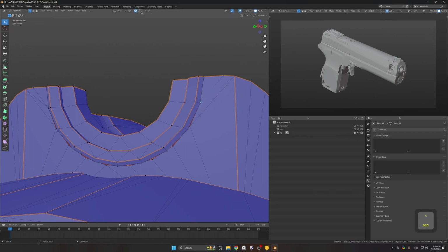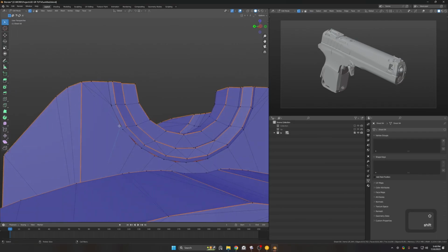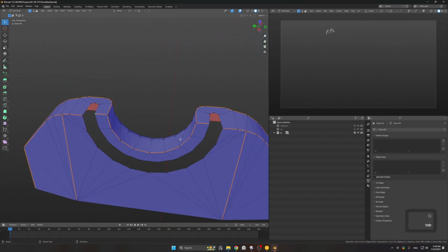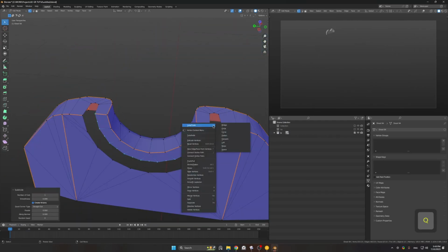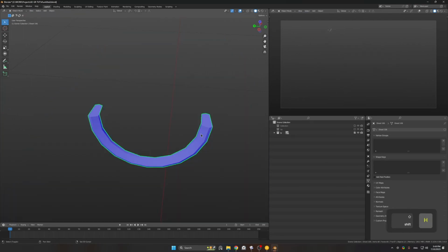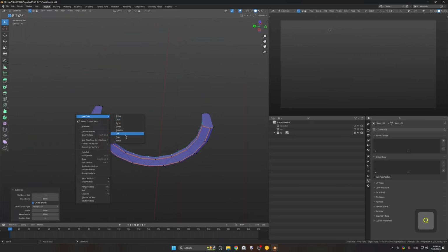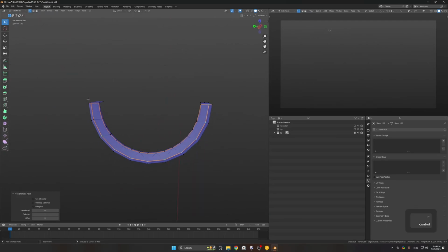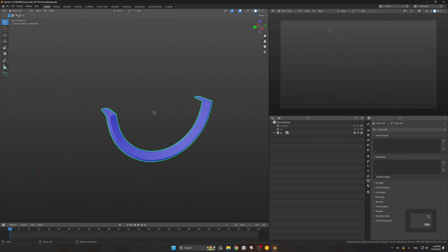Sometimes details that are close enough to each other will decimate with slightly different resolution, and that we will have to fix by hand. Let's also add a bit more resolution to it, since it's a very small object and it's going to be a focal point in the first person view. So I'm just going to quickly subdivide those loops and use loop tools to relax.